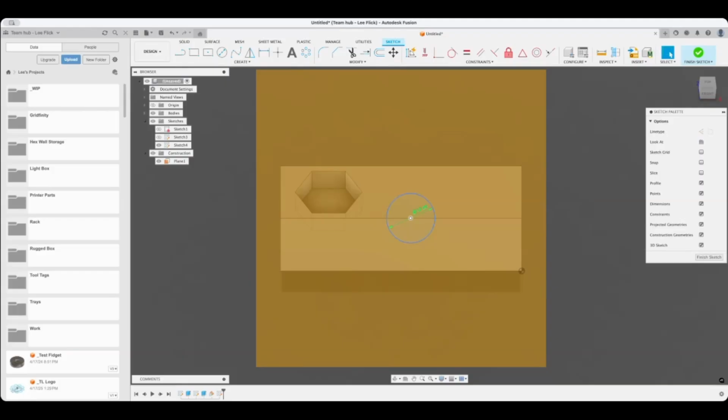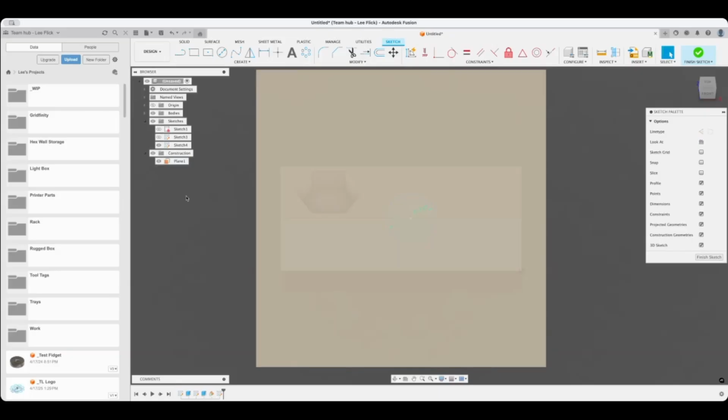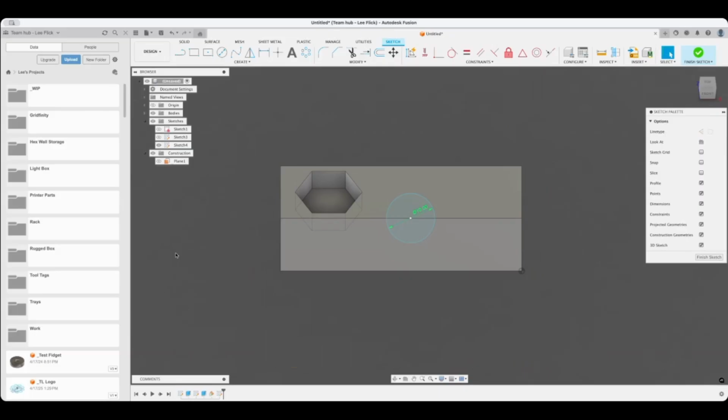So when I click on the blue and I click, hold on, let me go back. So I have the orange plane, right? And I click on it, it turns blue. When I hit create sketch, it disappears. The blue does? Yep. If you don't need to see it, fine, but if you want to see it, over on the left, turn on the plane. Okay, if you got it turned off, it's going to look like this. I like to see my planes when I'm drawing on them, but that's just me.